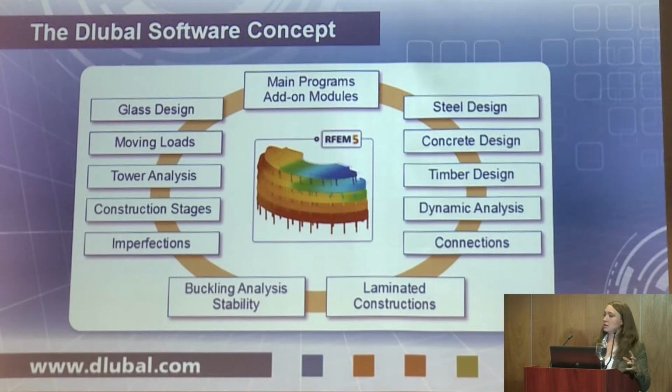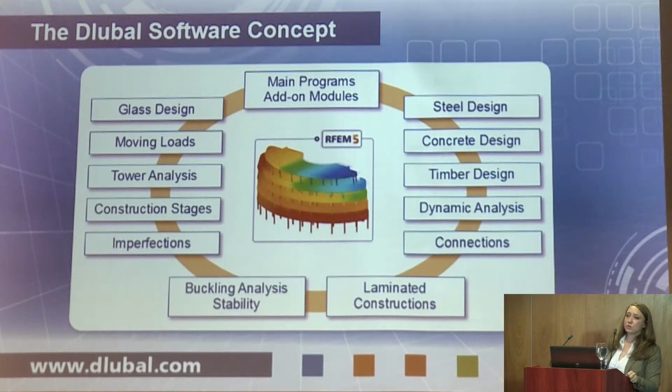We also have a package where you can model equipment and loads and design lattice tower constructions. You can perform, for example, analysis of geometrically nonlinear calculations with second or third order theory. Also imperfect constructions, where you can, for example, use buckling modes as an imperfection of the construction.